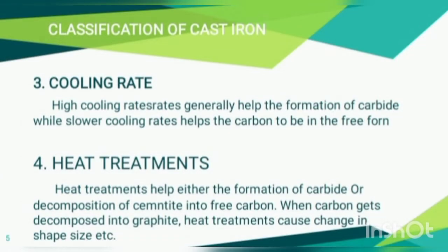And the third factor is the cooling rate during and after the solidification process. A higher cooling rate generally helps the formation of carbides, while slower cooling rates help the carbon to be in the free form. The fourth and final factor is heat treatment. Heat treatment helps either in the formation of carbide or in the decomposition of cementite into free carbon. When cementite gets decomposed into graphite, heat treatment causes change in the shape, size and distribution of graphite